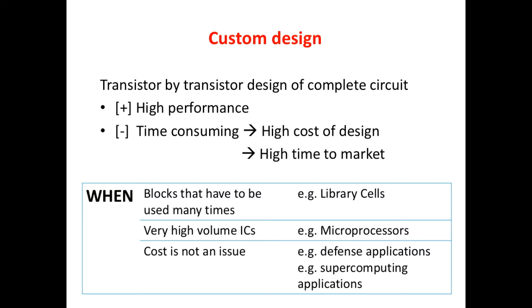So there are a few typical cases in which custom design is used, and actually are the ones that are shown here. Of course, you always use custom design for the blocks that have to be used many times. The standard cells that I mentioned before, they have to be designed at least once the first time. And of course, the design of the standard cell is a sort of custom design.